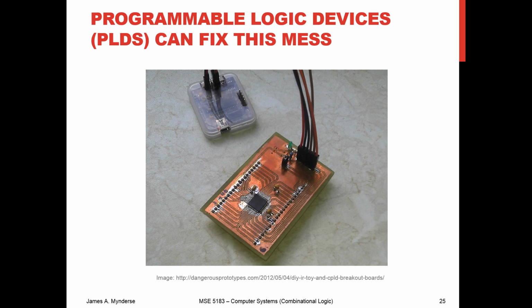So PLDs provide a nice replacement for this. They have the same sort of functions that your standard logic devices have, but they're like an Arduino, in that they're easy to program and easy to reuse. Not quite like an Arduino. The ones we had before were some Lattice ones where you had to have a specialized programmer that was considerably more expensive than a USB cable, and they had a limited number of reprograms. But still, a lot easier than that spaghetti wiring. Very similar to what you would use with an Arduino, but much faster for implementation of just combinational logic.